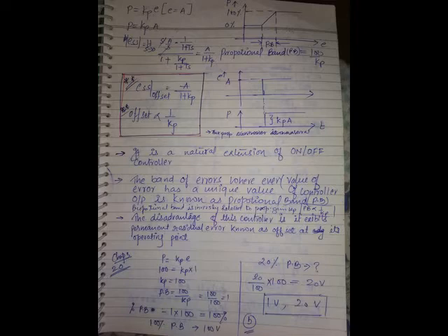It is 1 by omega Ti sin of omega t minus pi by 2. So you see, for sin omega t input, phase of the controller output is leading or lagging? How much angle it is lagging? pi by 2. What does phase lag mean? Is it a very fast response or a slow response?